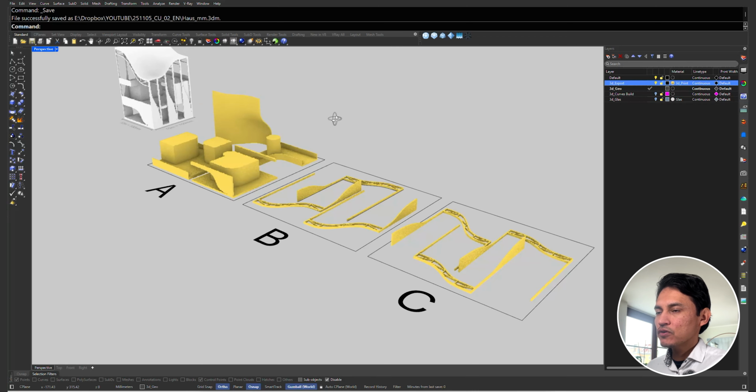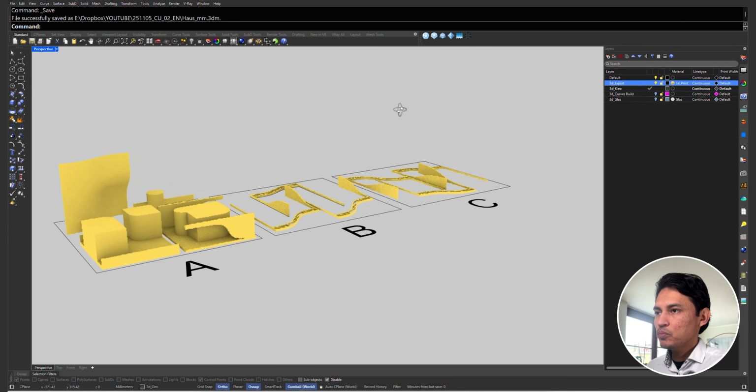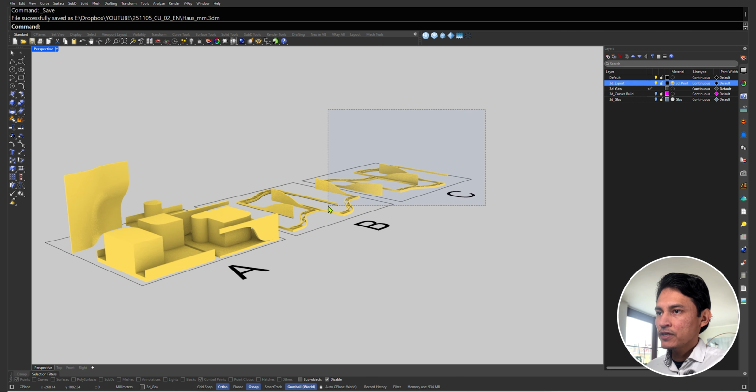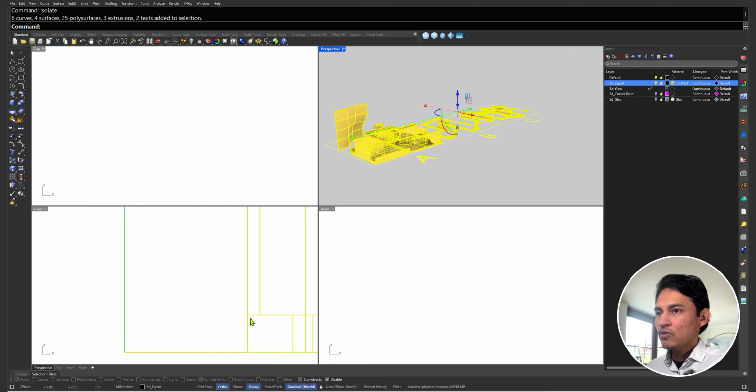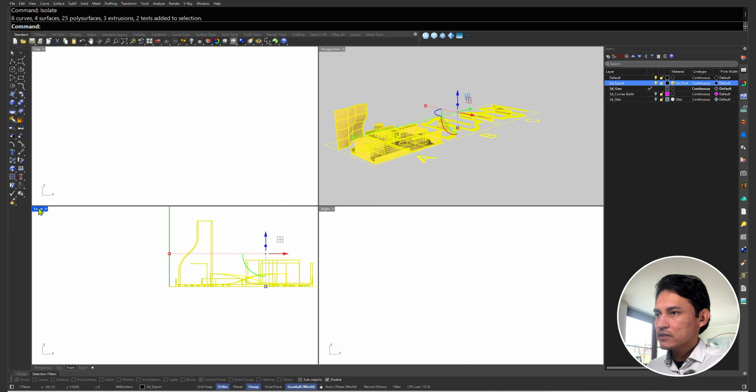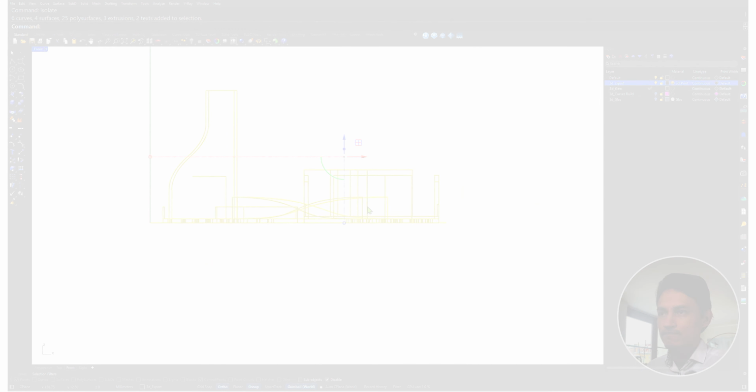So the best approach for this kind of models is to split them into pieces. Place them and orient them so that the bottom surfaces are touching the base plate of the printers, and with this avoiding as much as possible overhangs. If you have more than one printer, then you can organize the printing jobs so that they happen simultaneously, and with this reducing the printing time of the whole.